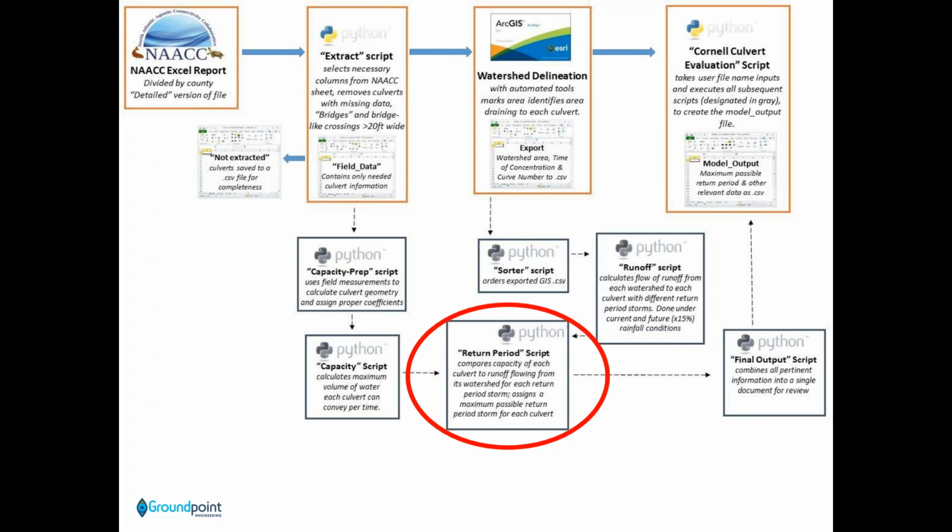One of the problems with this construct is that it's built on public domain USGS DEMs, which are part of the National Elevation Data Set. And that typically means 30-meter resolution, or if you're lucky, where I live in New York, perhaps you have 10-meter resolution, which is just a resampled version of the 30-meter. It was an academic project, so they wanted it to work. So they started with the 30-meter publicly available DEMs, and they filled sinks to get a depressionless DEM, and we're off to the races.